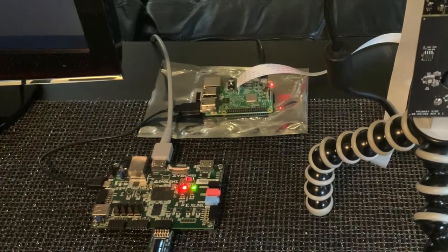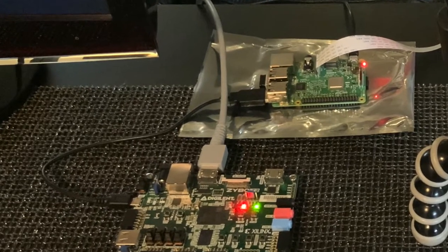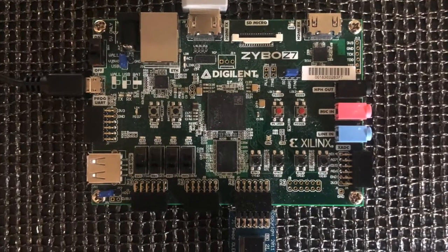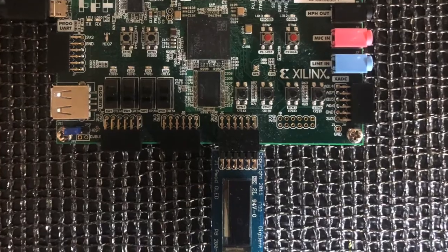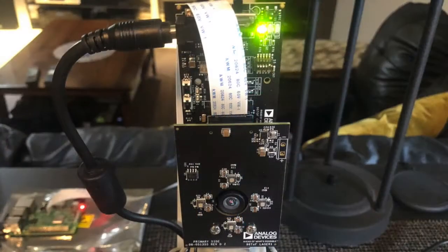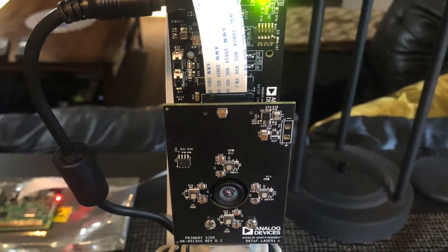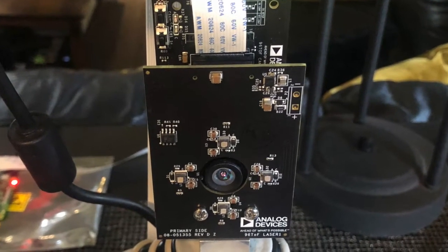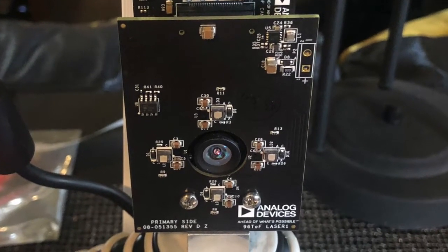Additionally, the board connects to the Raspberry Pi 3 board via a USB cable for serial data communication, as well as for sharing the power supply to the Pi. An OLED display is also connected to the Zybo board through its available GPIO to support user interaction by displaying informational messages about the system. Finally, the evaluation kit is used to carry out the DTOF process by emitting pulses of infrared light and measuring the time differences between light being transmitted and reflected to produce an infrared image of the scene, as well as to calculate the distance of the target object.